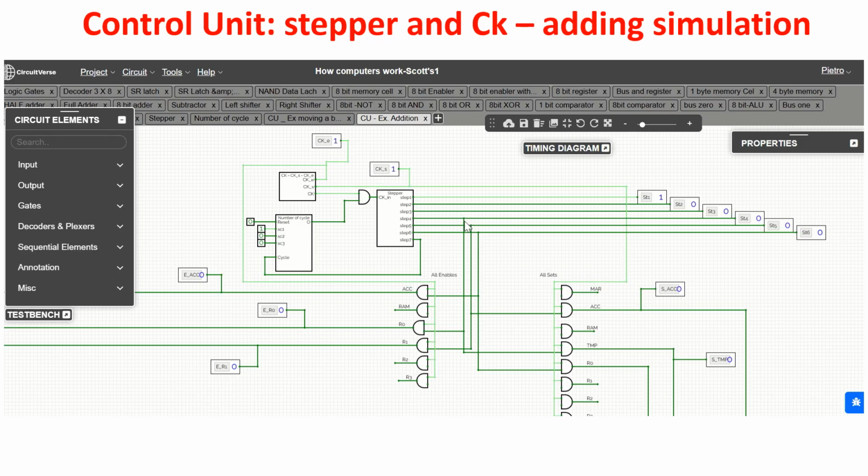Of course, for example, step 4 in our case is connected with an input of the AND gate, which creates the enable pulse to the register R0. So in order to create the right enable pulse to a register, we put in AND the clock E and the proper step. So if we want to give this pulse in step 4, we connect step 4 with this AND gate, whose output goes to the enable of the register R0, and so on.